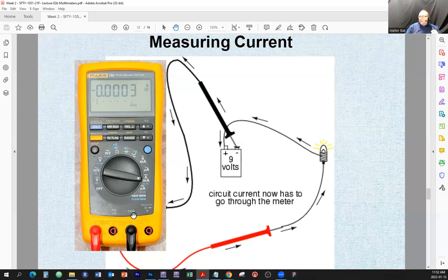multimeter is important, because if you connect it in reverse, the digital meter is going to show you a little minus that you have reversed the polarity. If you have an analog meter, it is going to deflect a certain way in order to accommodate the scale. If you connect it in reverse, it's going to try to deflect the needle backwards, and there's no more scale there. It can actually damage the galvanometer that is inside the meter. It can damage the meter, right?